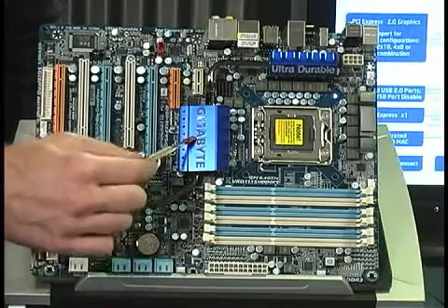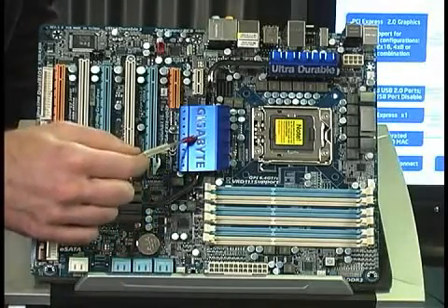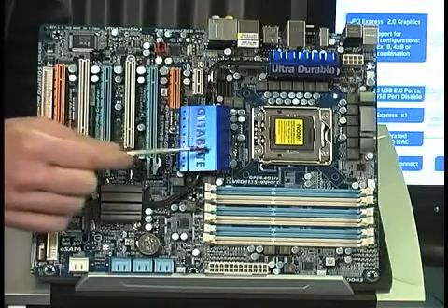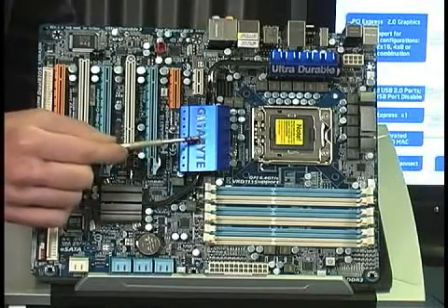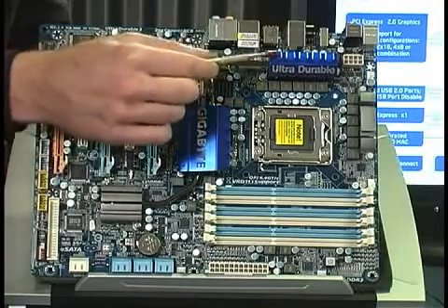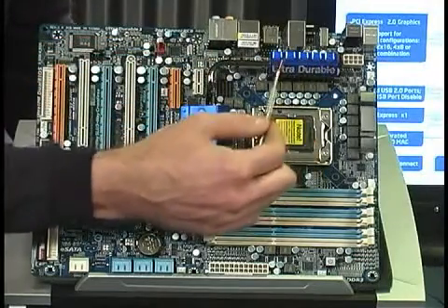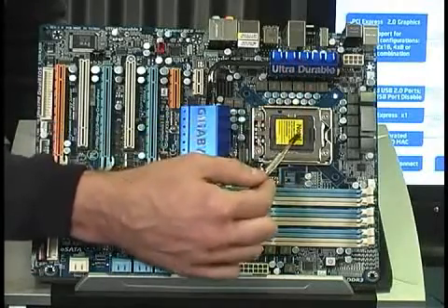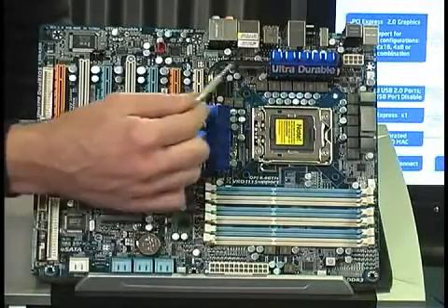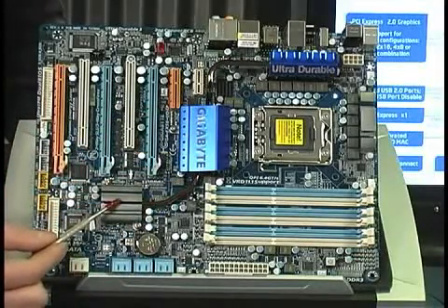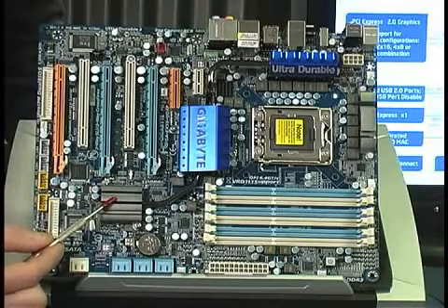Now, North Bridge chips in modern systems tend to run hot, so in most cases you will find some sort of a heat sink on them, as you see here. This heat sink is a fairly advanced heat sink. It has what's called a heat pipe that helps distribute heat among voltage regulators here. This is voltage regulator circuitry for the processor. It basically provides power to the processor. Then we have the heat pipe connected again to the North Bridge, and then over here to the South Bridge. This is the South Bridge component, also under a heat sink in many modern motherboards.